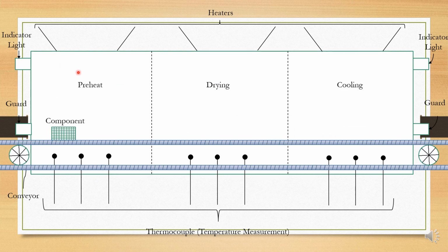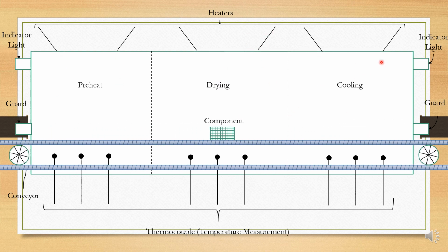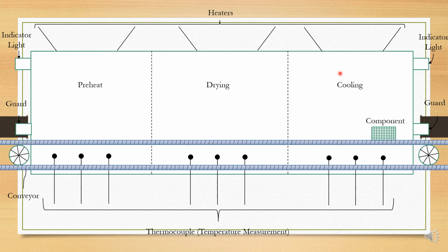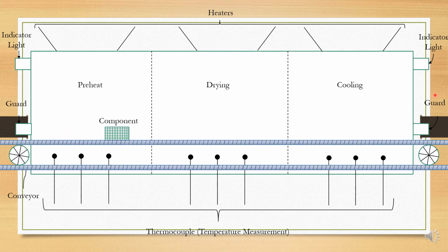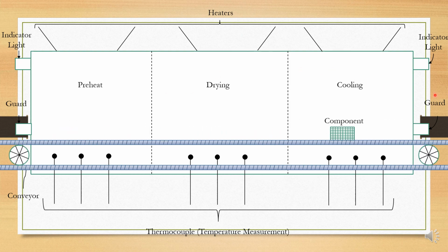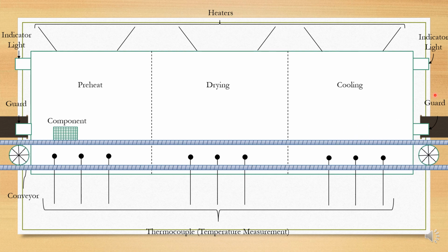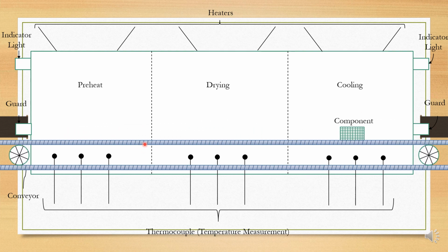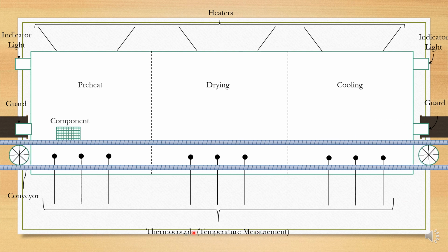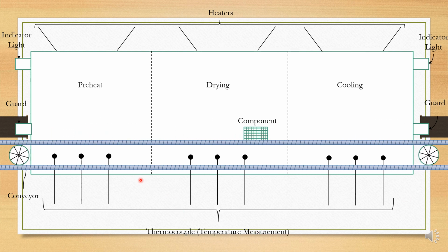The control unit at each heater area uses the PID control algorithm. We have one more function, conveyor failure: if the conveyor fails to start, the operator can issue a reset command, and then it shuts the whole system down. We also have a conveyor pause signal.